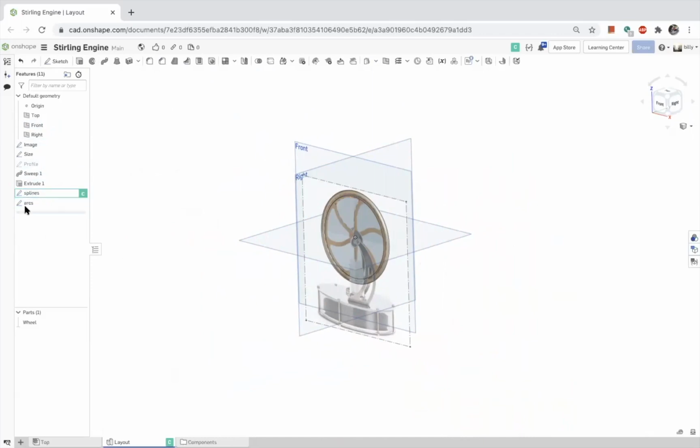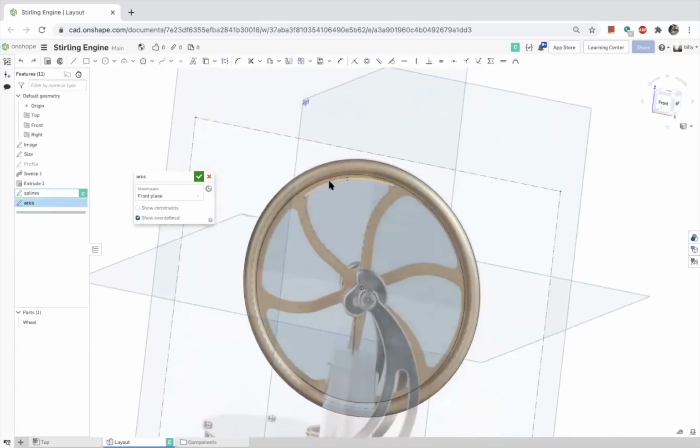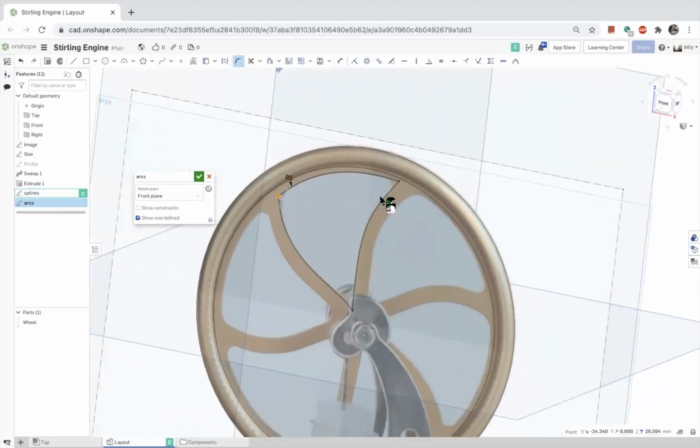And there are instances in life when you just have to control one and then the other. How do I get those over here? I'm just going to say use them. That's the U key. And now I'm going to force it to figure out what the arcs are. To do that, I need it to do a fillet. Where's fillets? Fillets. And we'll make them, they're probably all different.